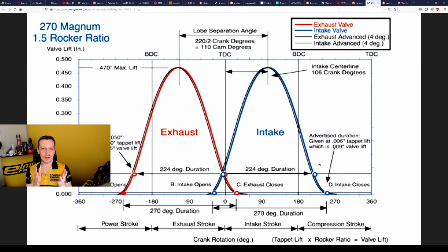For the ones in the RP968, for instance, it's just a circuit racing spec. So that's only 1,500 horsepower. It is a lot of power, but compared to the engine's capability it's not really that much, and we don't need to run any high boost pressures and don't really need any anti-lag and stuff like that. So it's just running plain stainless valves on the RP968. That's also one of the benefits of doing good designs.